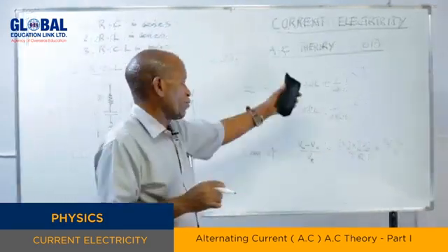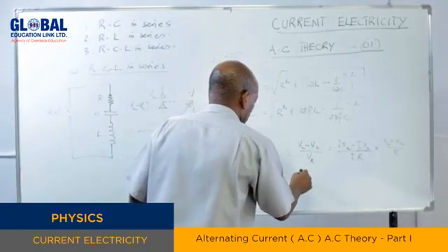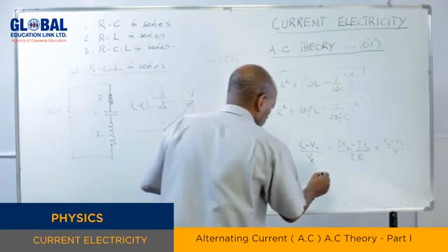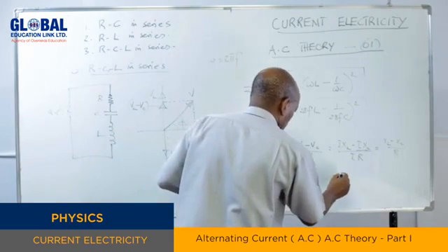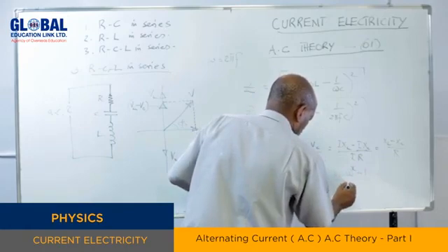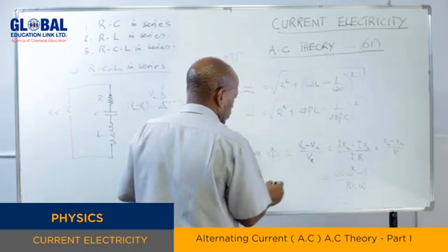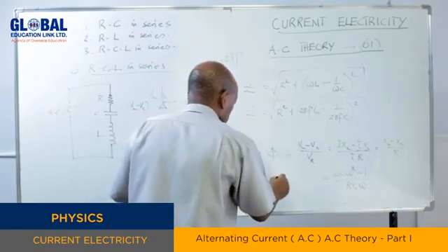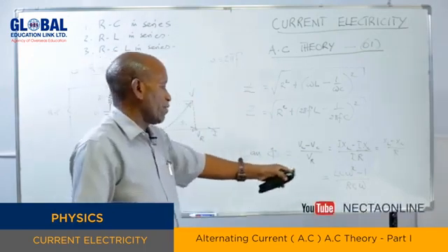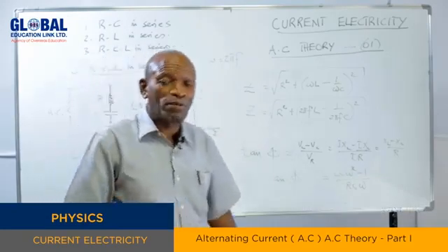Okay, so if you go about deriving this, you will find that this expression is equal to L C omega squared minus 1 over R C omega. So this will be equal to tan theta. This will be equal to tan phi. And phi will be equal to the inverse tan of that, where that particular angle theta of the applied voltage can be obtained.